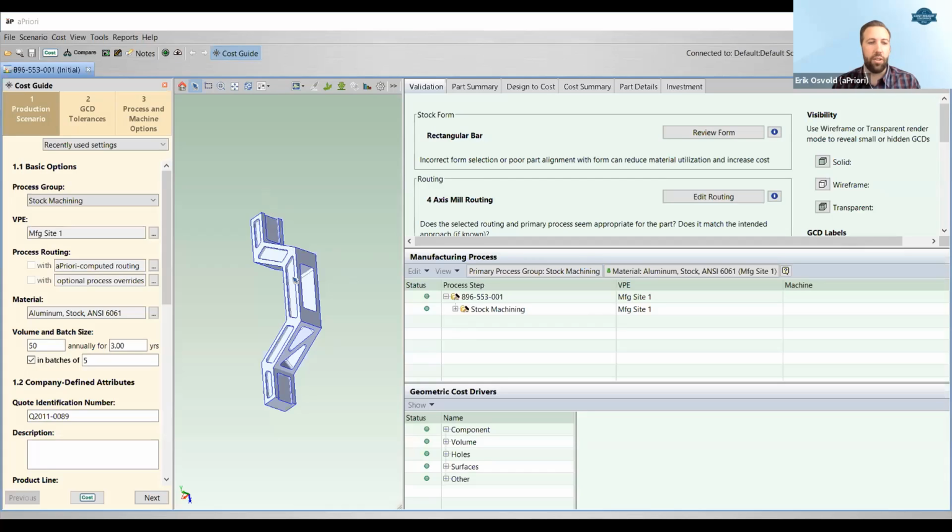To add additional tags, and it's really good to add tags to the data in order to leverage it in a meaningful manner in Cost Insight Report, you would go to System Admin Toolset, System Administrator, and User Defined Attributes. Then within here, I can add as many attributes as I'd like, and you can make them searchable and things like that.